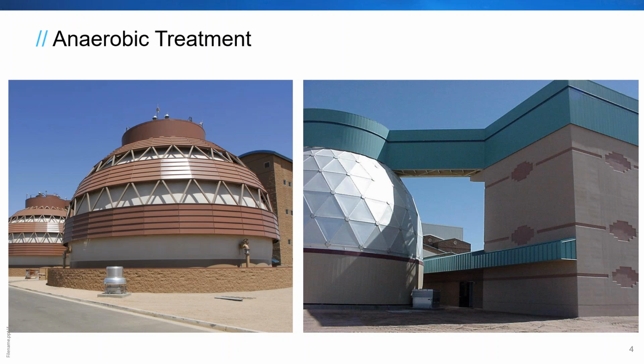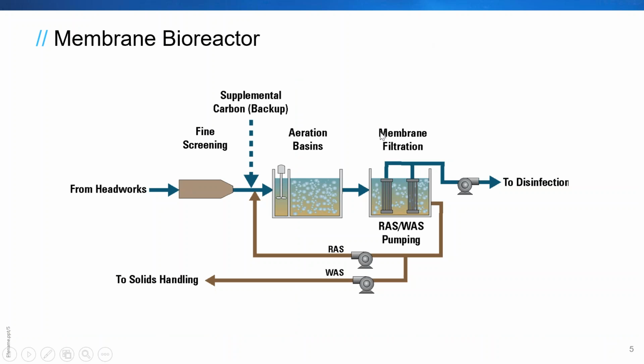That's where it gets interesting when you start coupling with MBR treatment, especially when you're looking at building it from small up to large to prove out the concept, right? Now, anaerobic treatment is not common, though, in the liquid stream. You typically see it, like I said, for the solids treatment, right? So now we're talking about, for anaerobic MBR, bringing it into the liquids mainstream. So again, it's a little bit of a different configuration than we might be used to on the municipal side, at least.